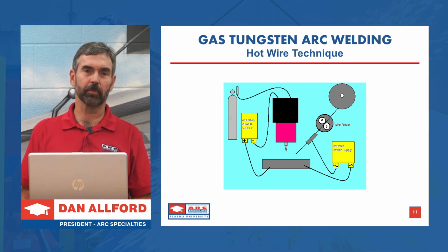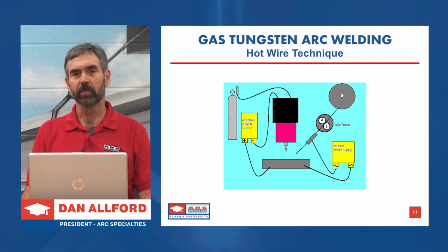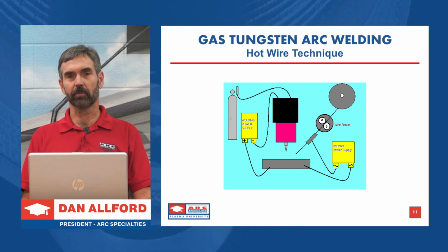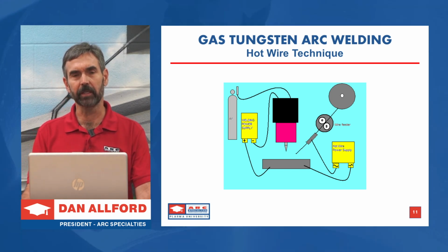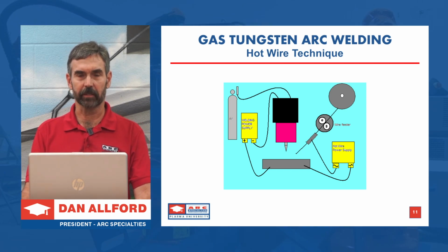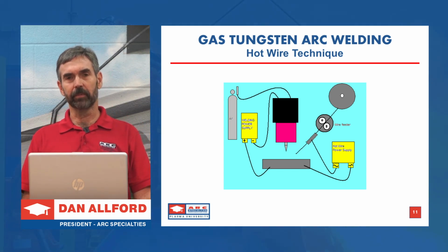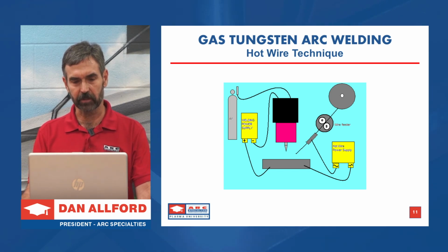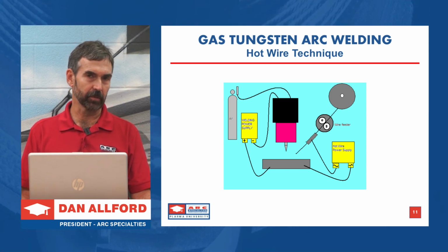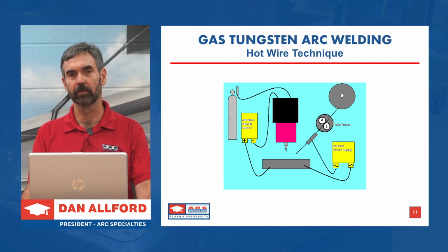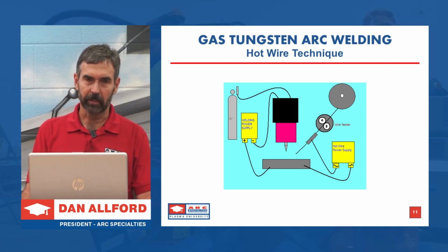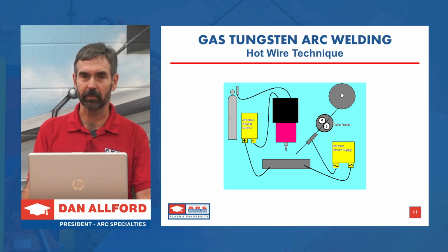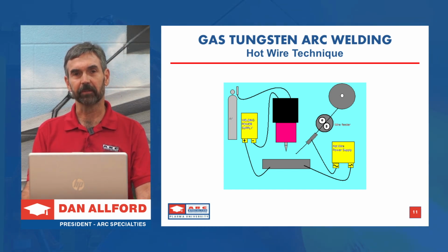In the welding business, productivity is measured in pounds per hour. So if we can add additional wire into the puddle, we increase the deposition rate, we increase the pounds per hour. One way to do this without increasing the heat input to the weld is a hot wire technique. This is something that was invented many years ago, and it doesn't complicate the systems too much, but it drastically improves deposition rate, it improves dilution, it's all around beneficial. So what we've drawn is a second power supply, and this preheats the wire as it flows into the puddle, which increases productivity of the welder.